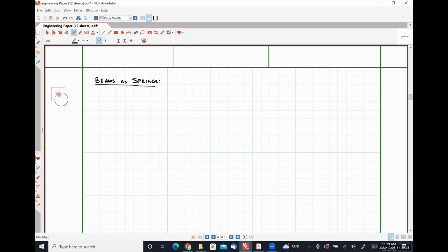There are 4 types of springs commonly used in MEMS devices: the extension rod, the cantilever beam, the guided beam, and a torsional spring. I only got far enough in my notes to talk about the derivation of how extension rods and cantilever beams work, so we'll pick up the other 2 on Wednesday.